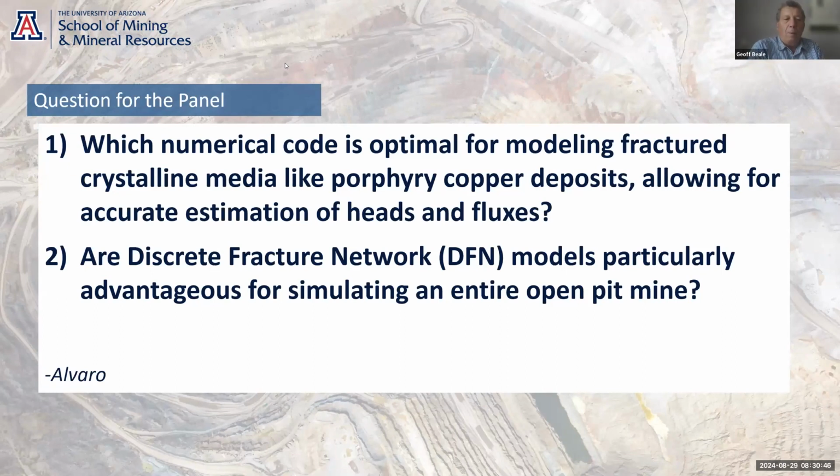And what matters for flow on the fracture isn't the average aperture, it's what we call the pinch point on that fracture. I always illustrate that if you have a flow of water down a 6-inch pipe with a 2-inch valve, it doesn't matter what the size of the pipe is. The only thing that controls the flow is the 2-inch valve. It's the same with fractures. If the fracture is tight in a certain area, that will control the flow.